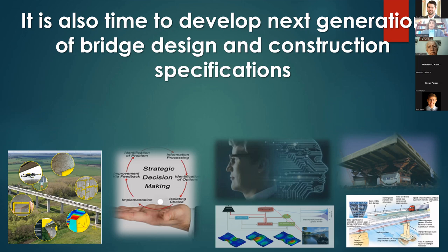And then in the 80s, a group of engineers gathered in the US and said, it's time for us to develop a load resistance factor design specification. And it took about 20 years or so before the AASHTO LRFD bridge design specification became well accepted by all the state DOTs, little by little. But it was a step forward. And the standard specification, which is allowable stress design, is no longer maintained, and nobody is using it anymore.